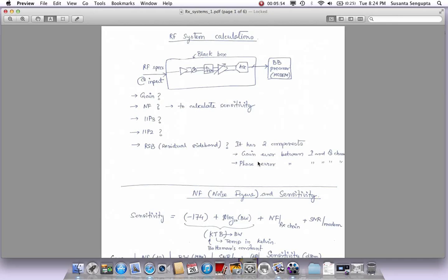In those kinds of systems, you're always going to have some gain error and phase error, which will give rise to a similar phenomenon where the image that we're trying to cancel in superheterodyne receivers will have finite image rejection. So I just wanted to mention it, but I don't want to distract you from this. We are talking about zero IF systems, and we are talking about the gain and phase error between the I and Q channels. So we'll look at each of these in more detail.